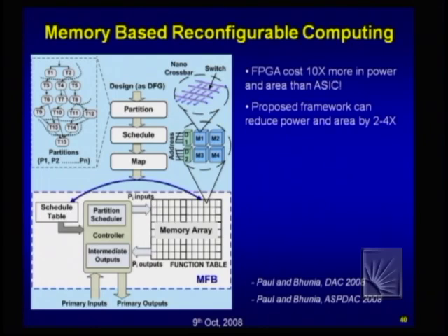So we developed a methodology to implement reconfigurable computing, and this is called memory based computing. In this computing, the idea is to use a huge memory array and compute the signal processing functions using lookup tables. So you have a 2-dimensional memory array, you store the functions in the form of lookup tables in the memory array, and then use a central controller which is very small to read the lookup tables in sequential and topological manner. So that's called memory based computing. We have introduced it and we have got several publications on that, and it turns out that such a memory based computing framework is reconfigurable, very low power, much lower power compared to an FPGA, and can also have less area, because if you have a high density memory array, then you can do resource usage much more efficiently.